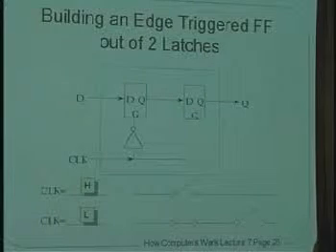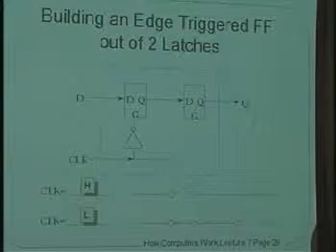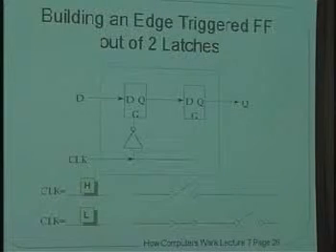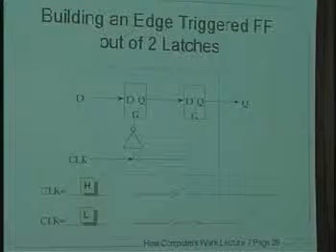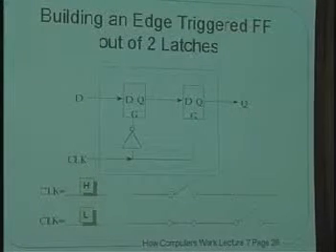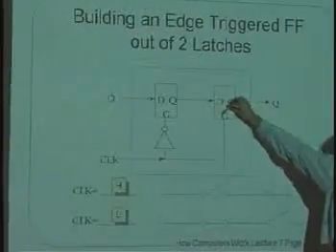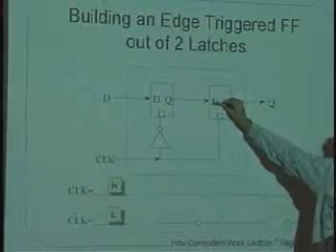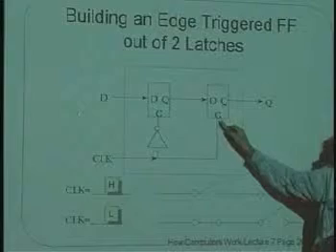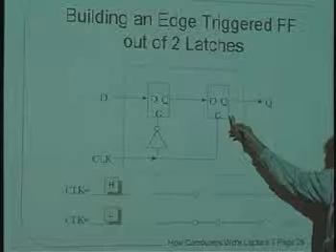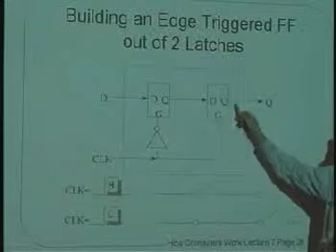Yeah? If you can do that on this, why couldn't you do it on the earlier one-to-one hazard state? Why do we need to build in the third AND gate? Because the hazard, what you're talking about, is the hazard that made it difficult to switch this thing here, right? We needed to do something when we were in the intermediate state. Okay, so what these circuits do when we're in the intermediate state where both G's are off is that they hold on to the old value there because they themselves are memory elements.